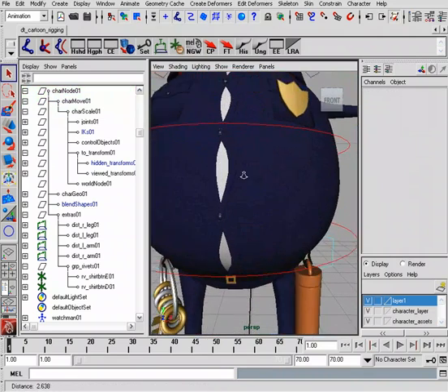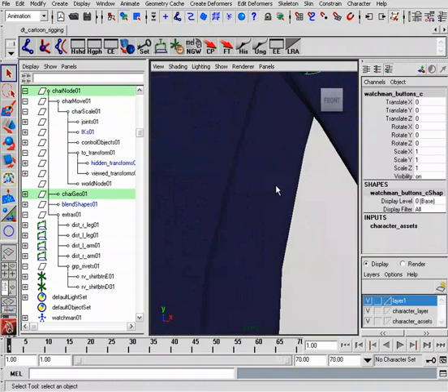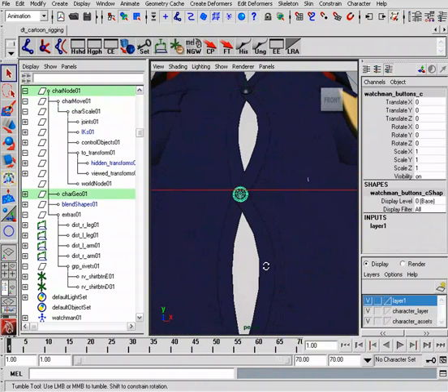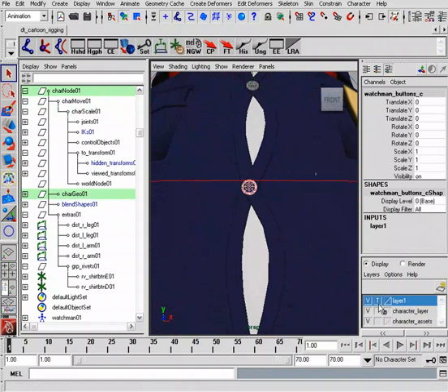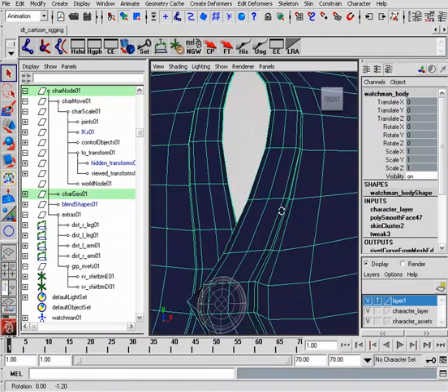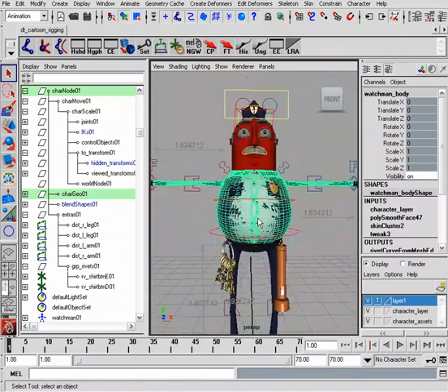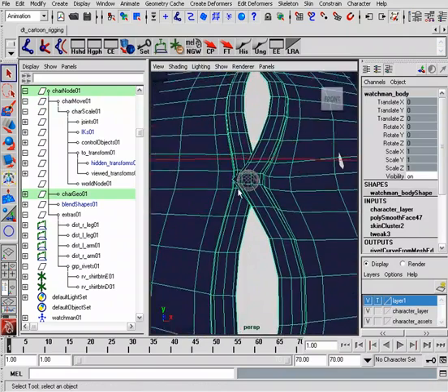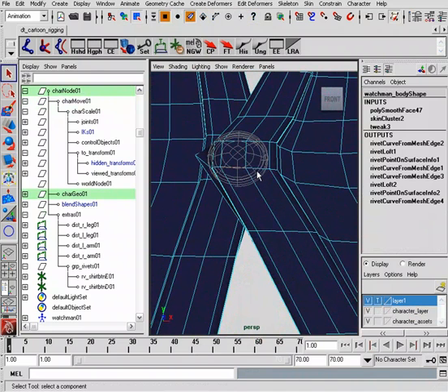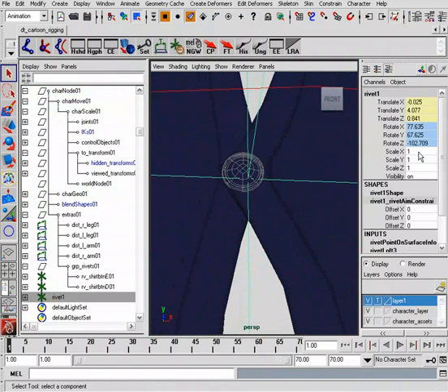We can go ahead and continue moving on now to the next button, which is right there in the center. So we'll continue along with that. Okay, add selected objects. Then we want to make sure that that's going to be templated. The button. We'll select our mesh. We could even frame it so it's not going to move from us. We'll go to our component mode, select our edges, apply another rivet, scale it down so it's not so large,